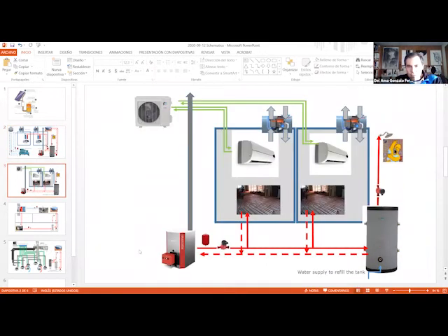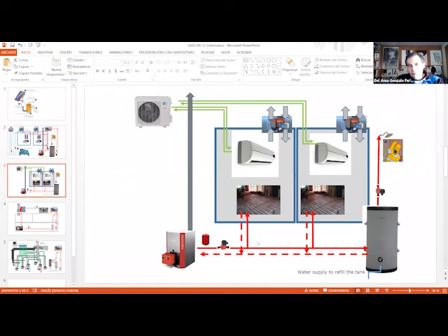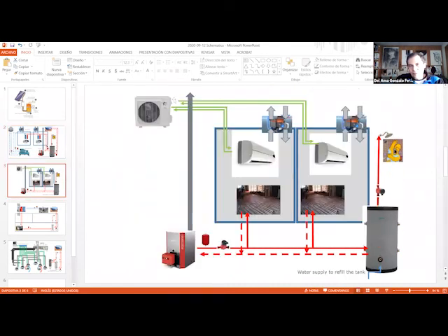What's this? So that's a different system. So that can be the system for a large building because we have this chiller. Here we don't have a chiller and we have a split system. So you see that we have the indoor split unit here. We have the outdoor unit here. So that means that this can be a residential building because we don't have chillers, especially if we don't have this kind of chiller. Residential buildings use split units. It's very unlikely that commercial buildings are using split units. So when we have this, we have either office buildings or residential buildings when we have split systems.